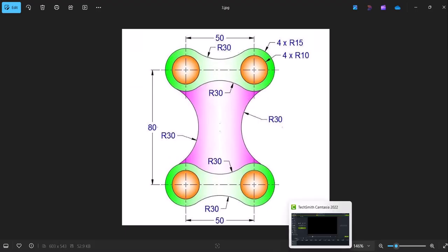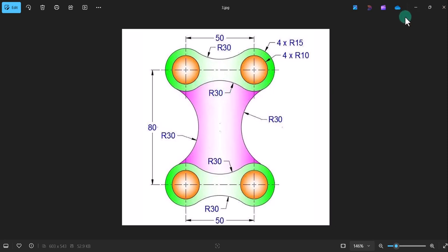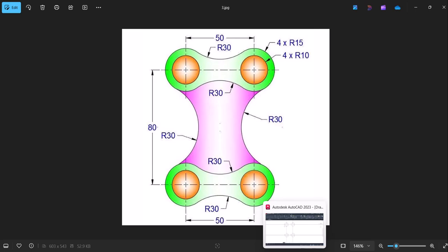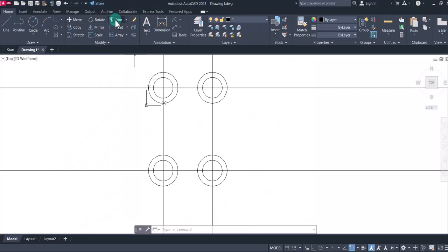All right, after using the copy tool, the next tool is to combine these two objects. By combining them, you can see we have given radius 30. So there are different ways I can do this. I can use arc, but there's a very important tool to be used here, which is fillet. So with fillet, I can combine these two objects using fillet of radius 30. That's a very easy way to get this done. So radius 30. So I'll click on fillet.